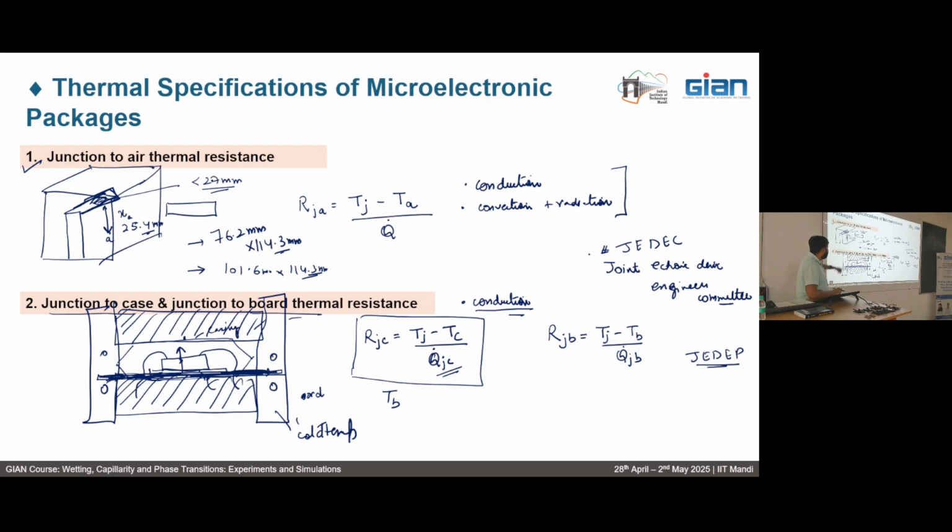So see, what will happen is that in this case we expect natural convection. So natural convection will affect the temperature which is above this device. So as to have a fair idea of what is the mean temperature in the whole box, that's where we keep this thermocouple. So it's waiting for the entire environment to come to steady state, but it has certain openings as well. And this is just for the natural convection.